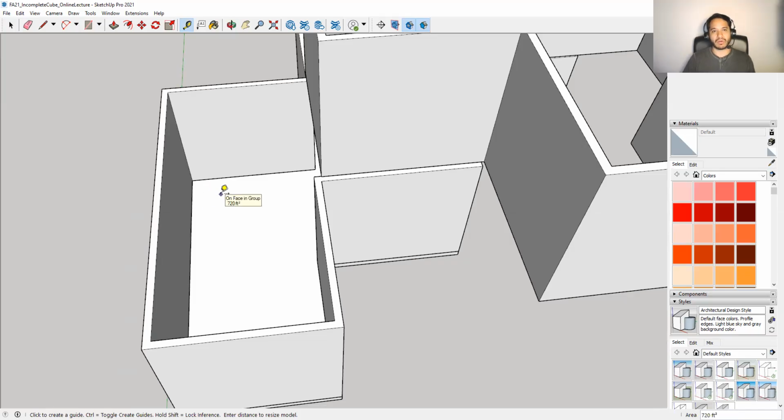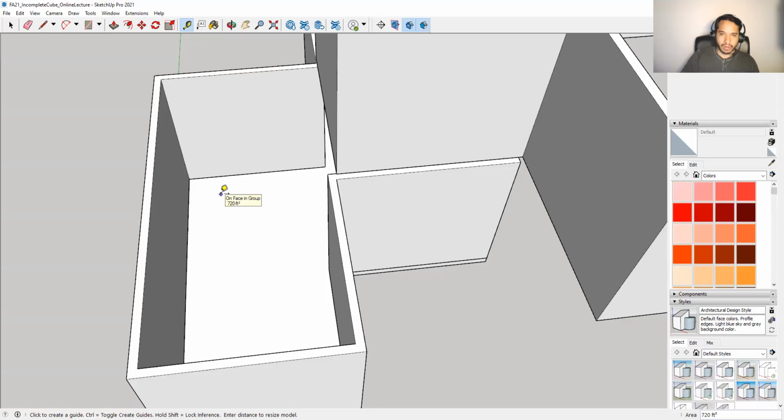Because at every corner, whenever you turn a staircase, so if I'm going up one way and then I have to turn and continue going up, at that corner, you're always going to need a landing. You're always going to need a place to land on, turn, and then continue going up. Those landings are 3 feet wide, so they're going to be 3 feet by 3 feet.